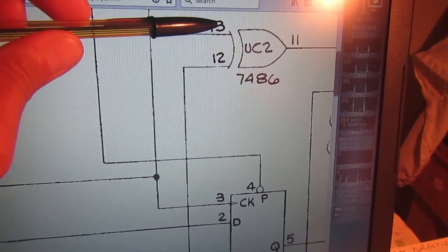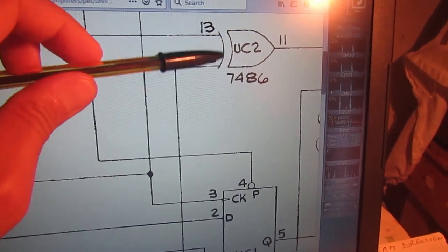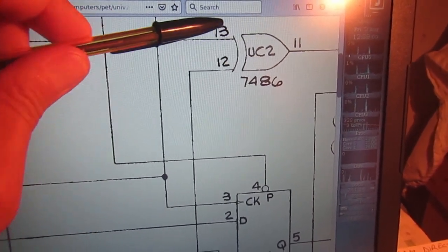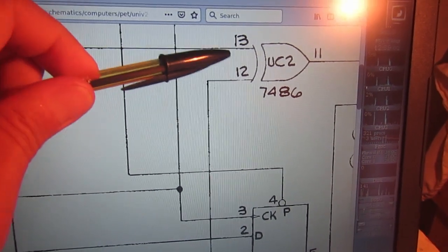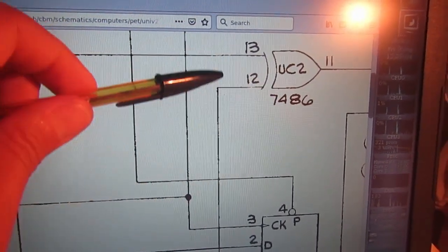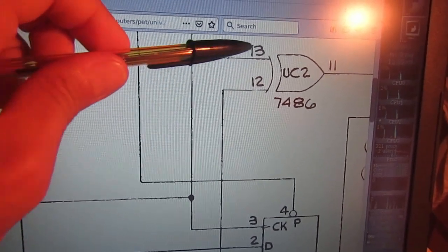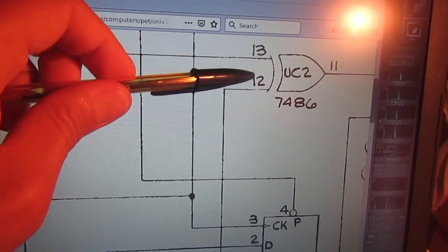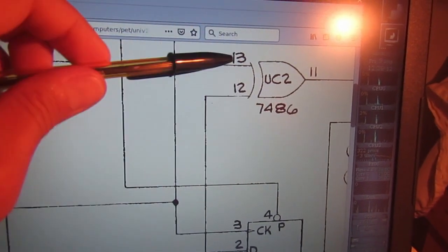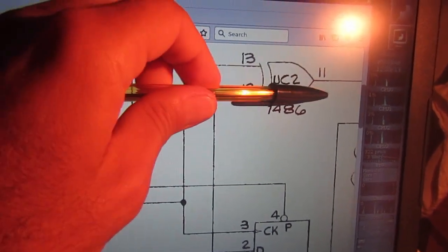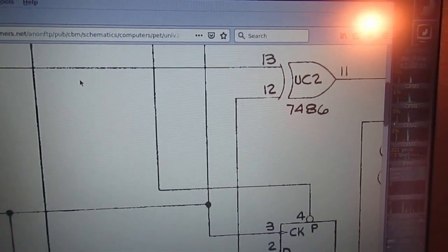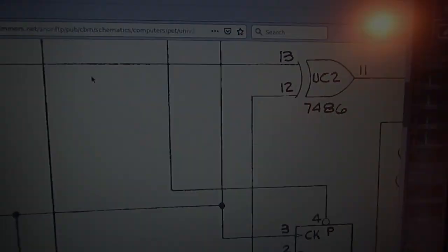If this is 1, the video signal gets inverted. This configuration is called an optional inverter, in fact. So that means that if we set on a location the 7th bit as 1, the character will be inverted in the video generation circuit.